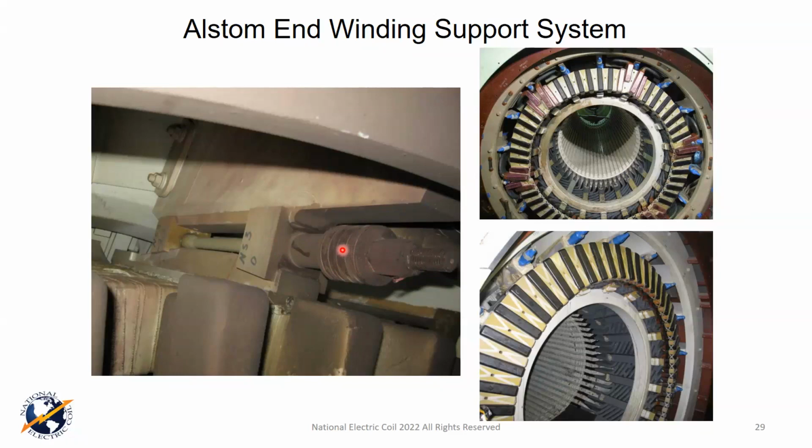We've upgraded them and made them a little bit thicker. We've made them out of a little bit different material so they don't tend to break, and so you can maintain compression. Once you lose compression of that Belleville stack, as you can imagine, you lose the compression on these blocks. If you lose the compression on these blocks, you're no longer effectively supporting the end winding, okay?